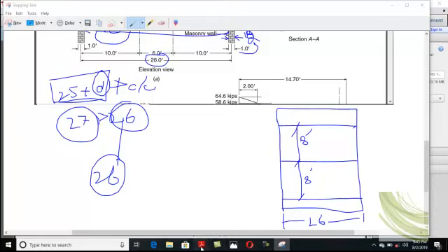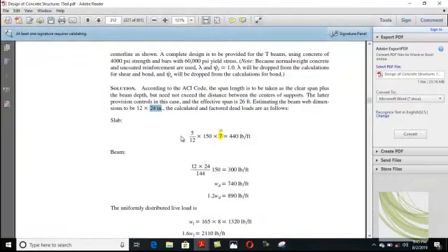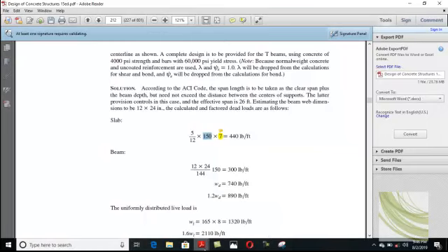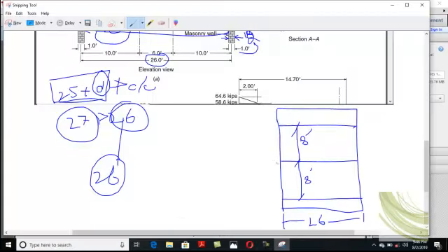Okay, so your slab thickness will be 5 inches. If you are interested in getting the weight of your slab, just convert your thickness to feet and multiply by the normal weight density of concrete, 150, multiplied by 7 feet. Now, where does this 7 feet come from? For this you need to understand your plan. Clear?